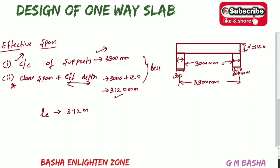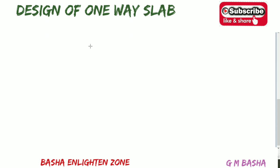So here I will explain the bending moment, that is the factored bending moment. Whatever value you get in terms of the factored load, therefore the bending moment. We all know the formula for a simply supported beam slab: Mu will be equal to w l square by 8.